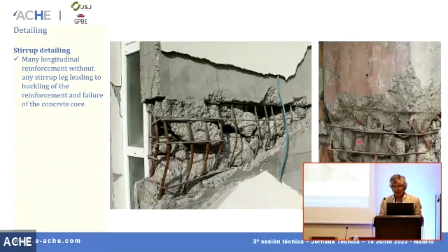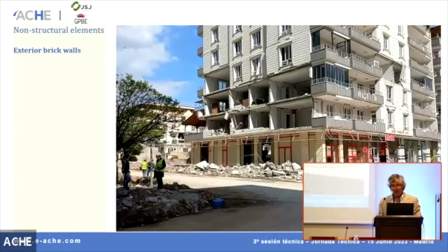There was another case, the lack of legs. Pedro Cabral also talked about this. We need more legs. You cannot have many longitudinal reinforcement without any stirrups. Otherwise, they will buckle. And something that we don't even think about, the non-structural, well, many people do not think.